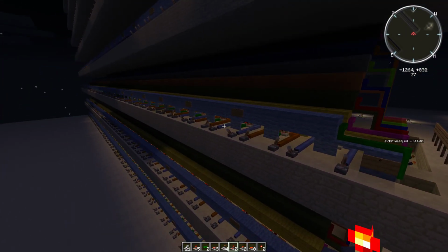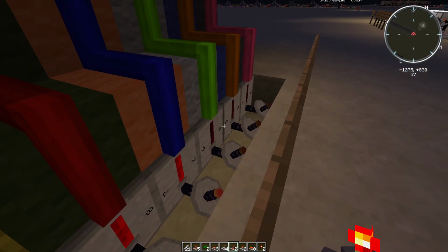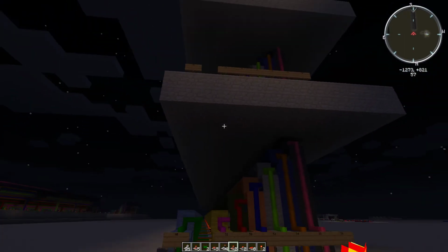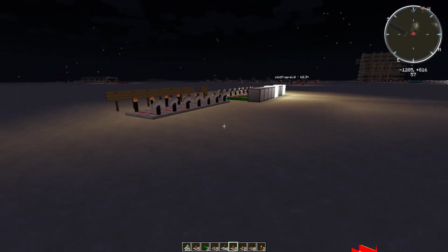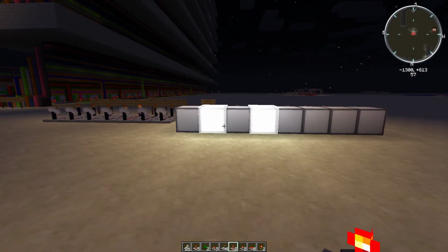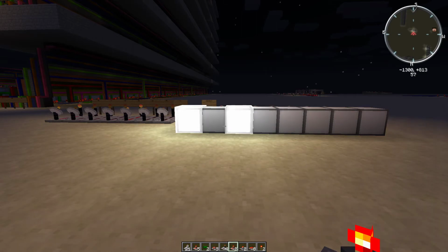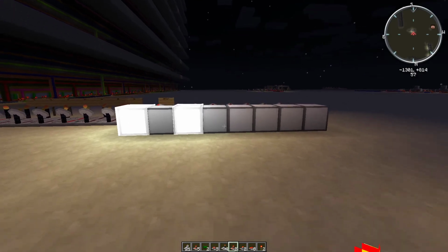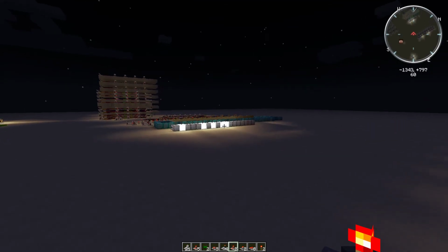So basically we have our selector pins going into here. This is where the program counter is entering in data. The program counter will select which byte it wants from the instruction memory, and the output of the instruction memory will be here. So right now, the first and third most significant bits are lit up because that's the instruction memory at that point in time. And this instruction will go into the instruction decoder.